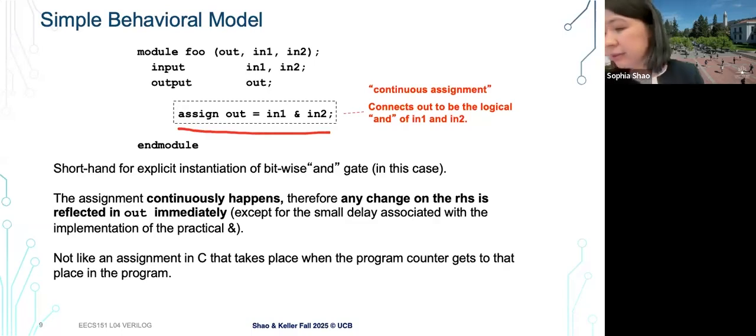So that's where you can use this assign statement. Here we're still talking about combinational logic, so there's no state here. We basically assign inputs, and then they can perform different operations. We'll talk about different operators later. All we do is express or describe the operation that we want to perform and assign it to the output signal. So this is a way to explicitly describe combinational logic using clearer and simpler semantics.